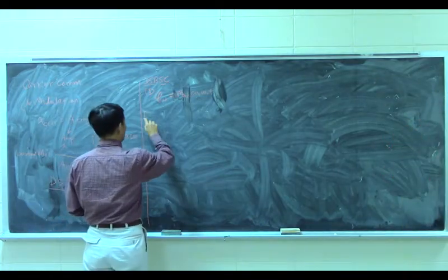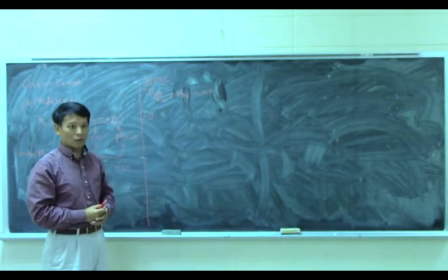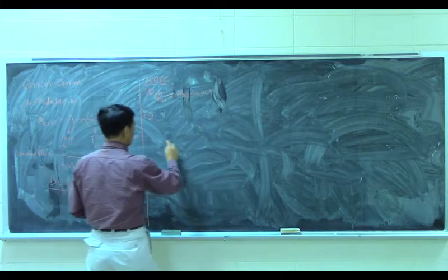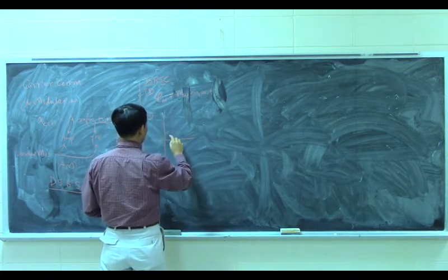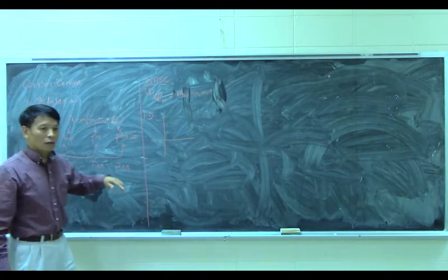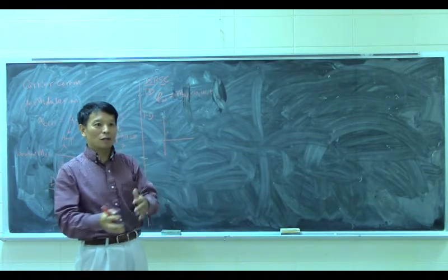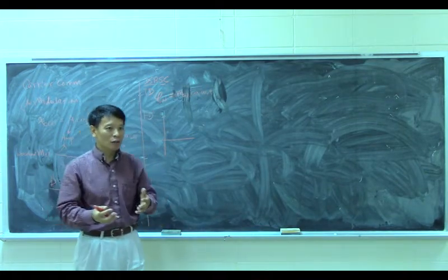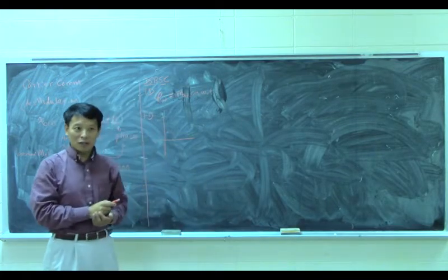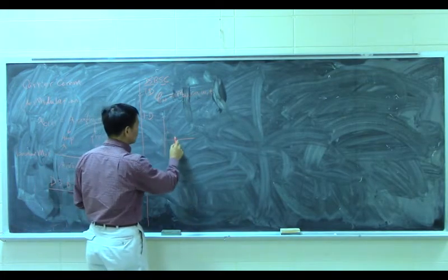Right? Now, let's see what this looks like in frequency domain. In frequency domain, suppose this is in time, the m(t) must have some spectrum, right? So the information transmitted has some spectrum. For example, my voice, that is like from DC up to less than 20K. That is a typical human voice, from 0 to less than 20K.